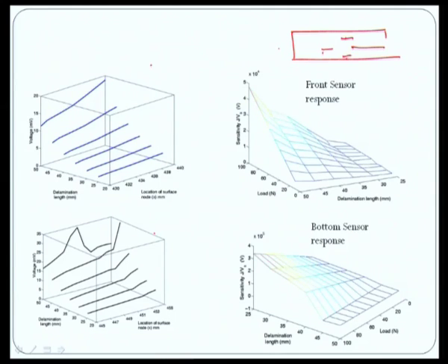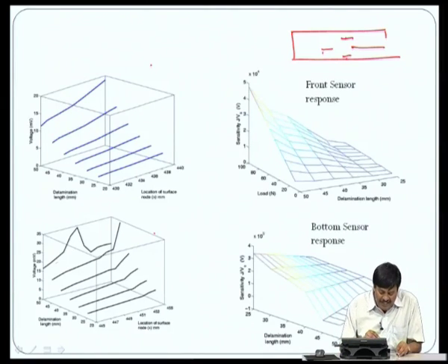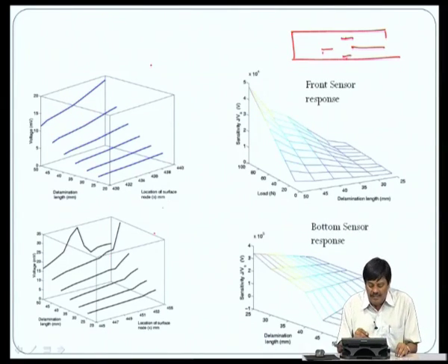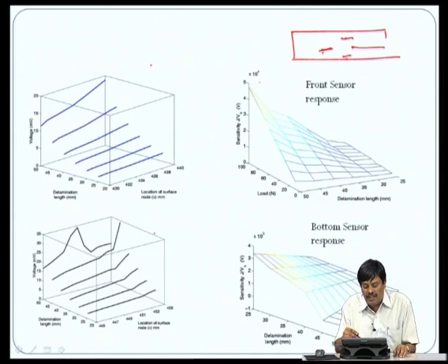This is one of the sensing applications. There are many applications that we can actually construct using the piezoelectric material. So, here we clearly see there is an increased peak in the response in the sensor 3, and based on that we can basically say that there is something happening. Even here in the front sensor we see that as the load is increased, as the delamination nears 50, there is a huge increase in the voltage. So, this is the sensitivity of the J integral. Basically, what we are saying is, if we just measure the voltage and if we have this curve, we can say how severe the crack is and whether there are any necessary repairs that we need to do to avoid catastrophic failure, which is very, very important from the structural health monitoring perspective.